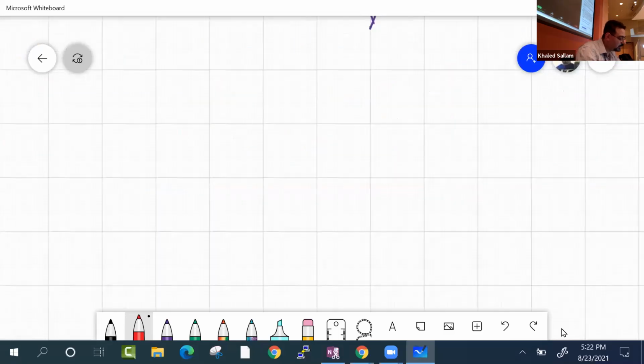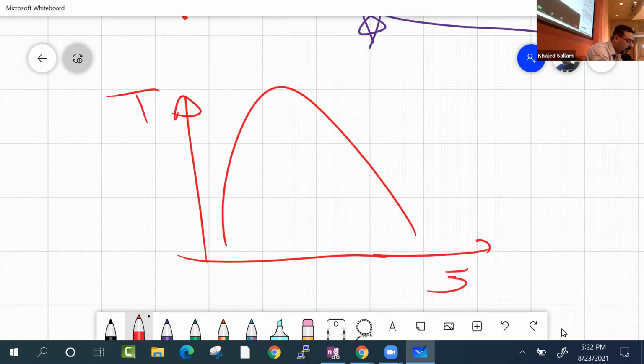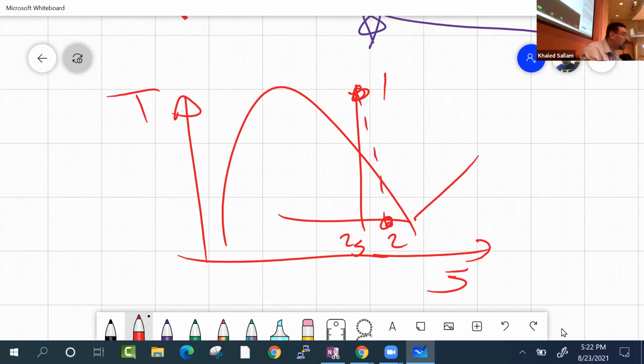I am saying that on this TS diagram, if I have this hot steam like this and I expand, this is 1, this is 2S, actual 2 would be something like this. So now to go to that same place so I can repeat, I'm getting more and more power.